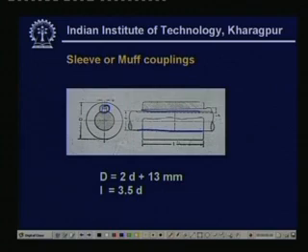Now, normally there are two situations. The muff or the slip is put on the top of the shaft by means of press fit or interference fit, or by means of keys. Now, oftentimes both the interference fit and the keys are used.